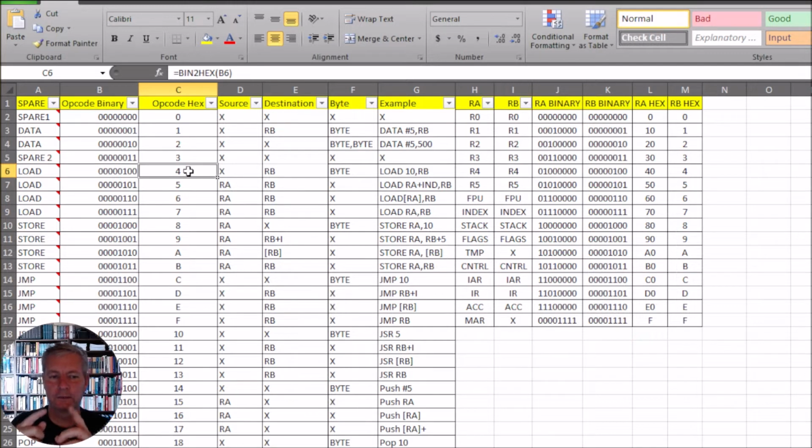It's going to be 4 bits that define it, so it will be 04 for the opcode, and there won't be any register A, so that will be a value of 0, but register B will be used. But if we're using register R0, that will just be 0 as well. So our code here is going to be 0400. That gives us the command that we need.